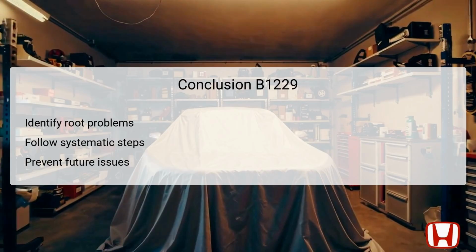Through careful diagnostics, via steps like continuity testing and monitoring of DTCs, technicians can accurately isolate and repair faults within the sunlight sensor circuit. Furthermore, incorporating regular maintenance practices ensures the longevity and reliability of vehicle systems, ultimately enhancing owner satisfaction. By understanding this process, both technicians and vehicle owners can be more informed and proactive about maintaining optimal climate control performance.